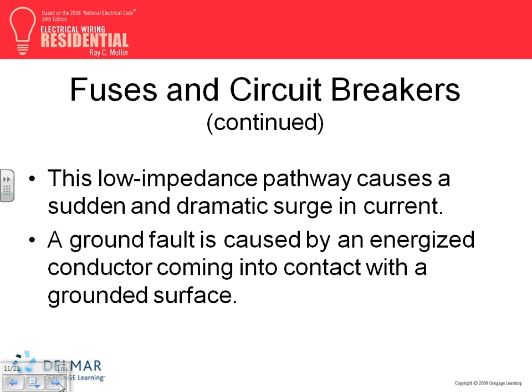So these are a few things. Okay, the way circuit breakers work, guys, is if you have a low impedance path, a dramatic surge in the current, the circuit breakers react. And I promise you, we'll talk about electronic circuit breakers versus thermomagnetic circuit breakers. In thermomagnetic circuit breakers, the magnetic part is for the short circuit. It sees a huge amount of current and creates a magnetic field that physically, mechanically opens the contacts in the circuit breaker.